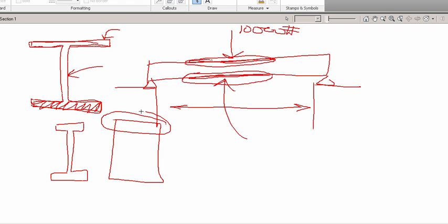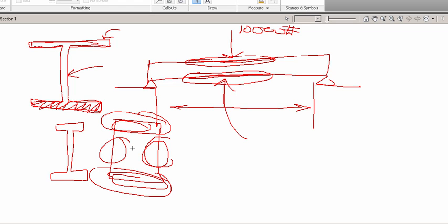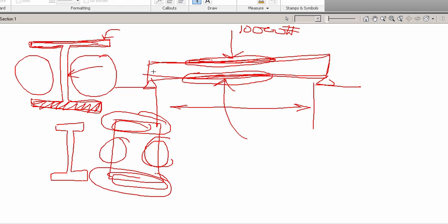The point is, a big old piece of wood cross section does have strength right here for sure, but it has a lot of wasted material in this zone that we don't actually need. So that's why the beams are shaped this way. We maximize where the stress is with material, and we omit material in these zones where we don't really need it. So that's why W-beams are so common, because they support long bending loads very effectively.